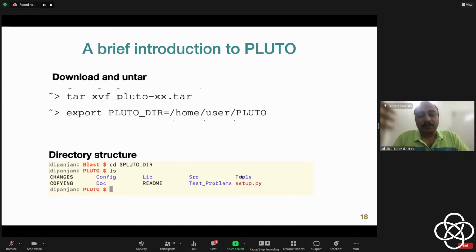And you can perform simple experiments like the Kelvin-Helmholtz instabilities, Rayleigh-Taylor instabilities, flows between different directions, etc., and learn how fluids behave. And the most interesting thing about fluids is that fluid equations are nonlinear because of this v dot del v term in the momentum equation that couples modes from different wave vector space into each other, and that makes things nonlinear.